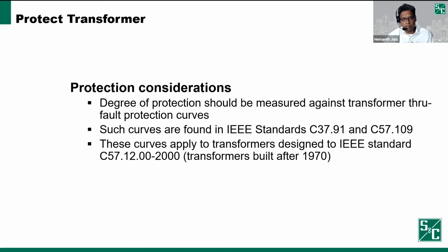Now, you need to see how the fuse that you're selecting protects the transformer and how well it protects the transformer. The way you do that is by measuring it against the transformer through fault protection curves. Those curves are found in the standards, and I list the standards up there. Manufacturers will also provide the transformer damage curves, and there is software available for free, such as SNC's Coordinate, which also has the transformer damage curves. And there is software you can purchase that also has the transformer damage curves.